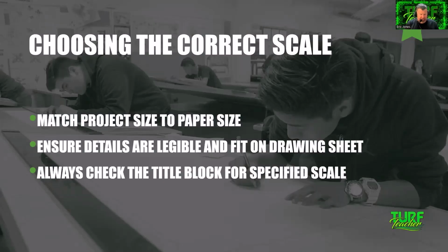Now, when I place it on my paper, I also have to leave room for my plant list, my irrigation parts, some details or whatever. It just depends on what it is that I'm drawing. If I'm drawing just an irrigation design, it may only be one sheet for the project. Site plan, got my landscape on it, drawing where my heads are and the zones. I'm doing that record drawing, as it's called. We call it record drawing because we're irrigation contractors. We don't call it as-built because we're not licensed engineers. But make sure your project matches your paper size.